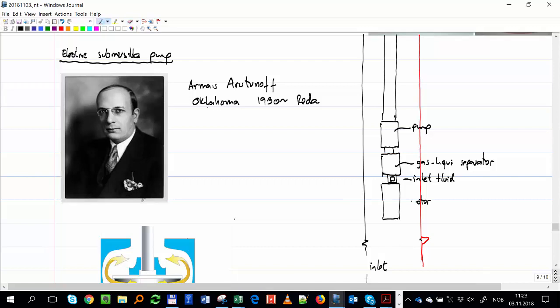And this is something that screws into the tubing, okay? Remember the tubing has some joints, so you just screw the pump onto the tubing. So that's the motor, and for the motor you need this famous cable coming up from the tubing hanger. So you make a hole in the tubing hanger. I'm going to show you a figure very quickly. Now, I make a hole and I send the cable down all the way to the motor.